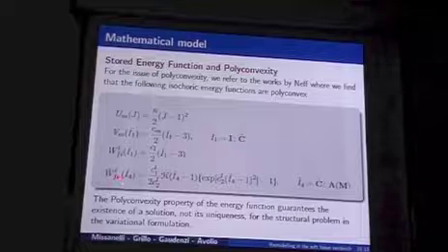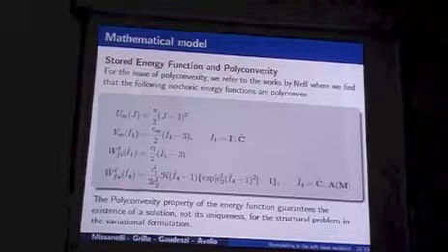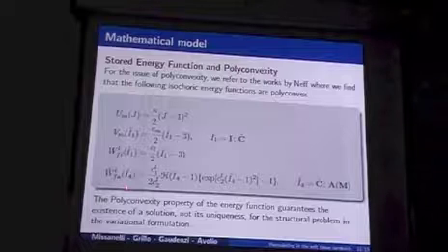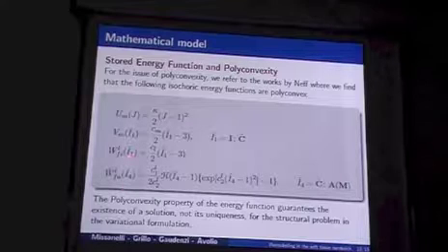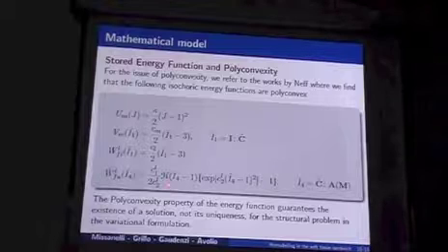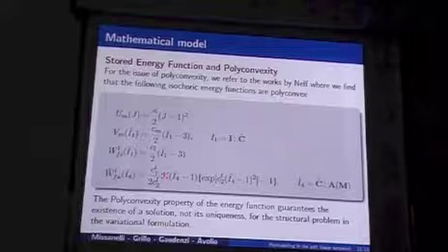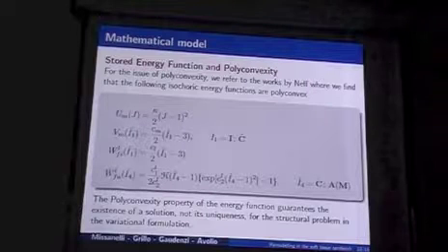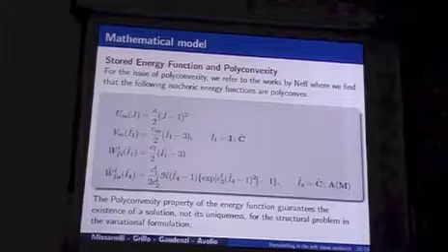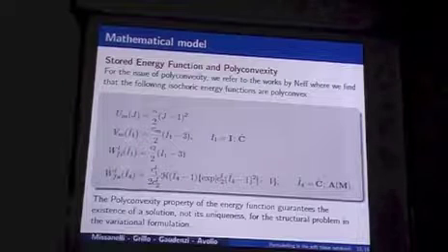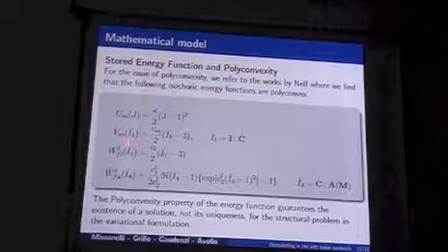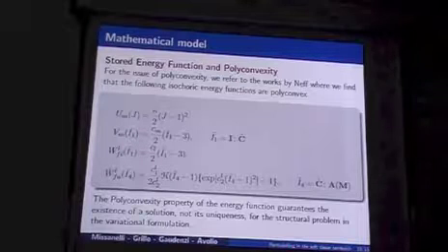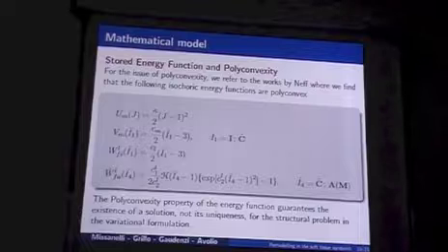And here, for the anisotropy that appears in the fiber, we have an activation function, a Heaviside function that is not null just when we have an elongation, not a compression, and an exponential function. All these functions are polyconvex, as we can see in the works of Neff.